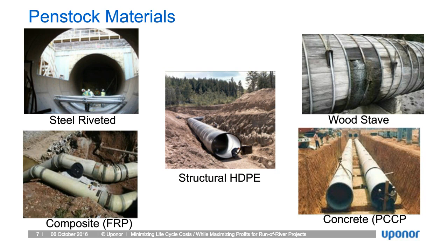Wood staves, again, are very inexpensive, but the downside is that wood doesn't have a very long life cycle. One of the challenges is that when wood is saturated, it will not decay or delignify. The issue is if you have to shut down the penstock and dewater, that's when the penstock starts to degrade. Wood is an inexpensive material, but it doesn't hold up very well to transient pressures and movement, and it does suffer from delignification from attack from the outside. So if you see pictures of wood staves, you'll see a lot of leaks occurring.